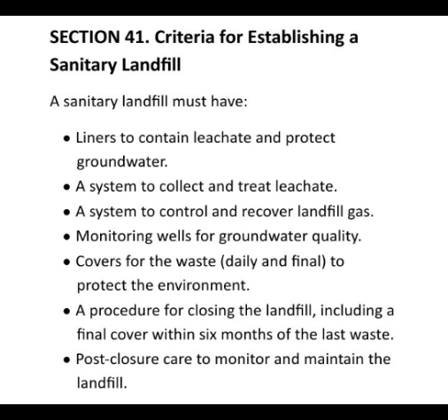for groundwater quality, covers for the waste, daily and final, to protect the environment, a procedure for closing the landfill including a final cover within 6 months of the last waste, and post-closure care to monitor and maintain the landfill. Section 41 explains a sanitary landfill must safely manage waste and prevent pollution. It should control harmful liquids and gases, protect groundwater, cover waste properly, and continue monitoring and maintenance even after closure to keep the environment safe.